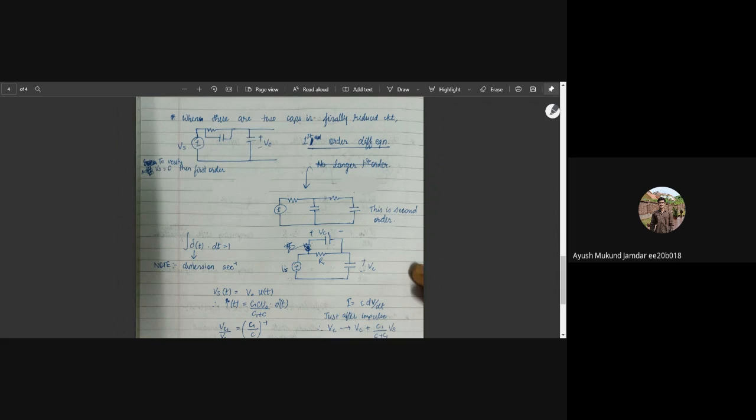So it is indeed still a first order differential equation, because the order of the circuit is the number of independent state variables that we can assign to the system. The two capacitors, although they might have different initial voltages, are governed and restricted by Kirchhoff's voltage law.